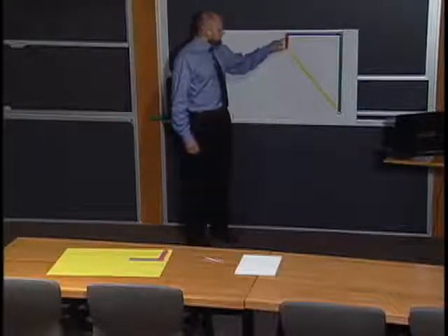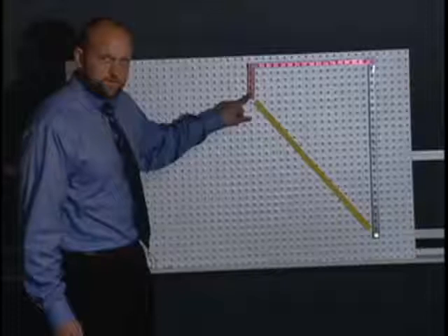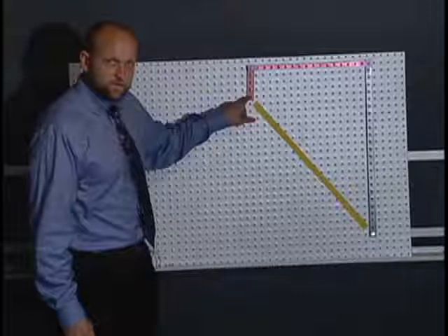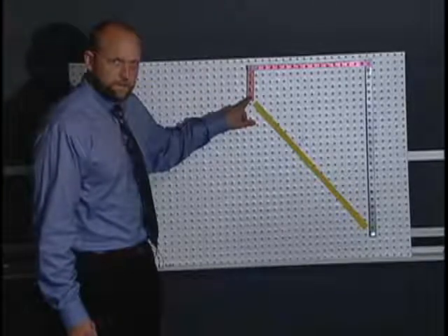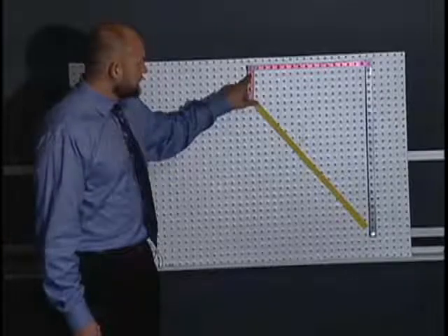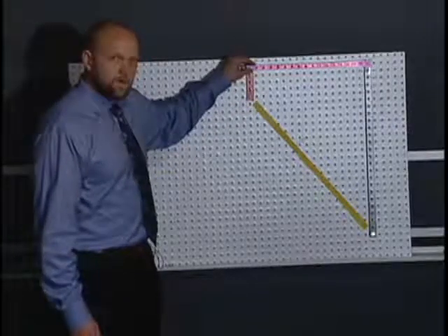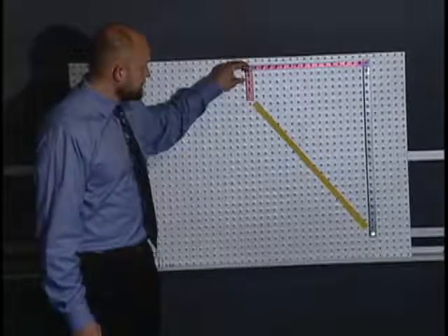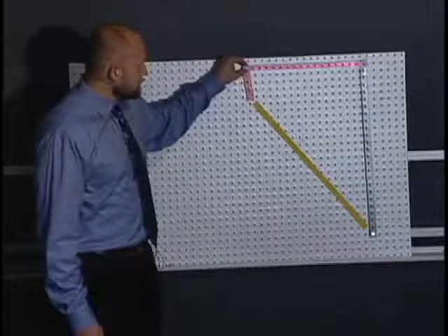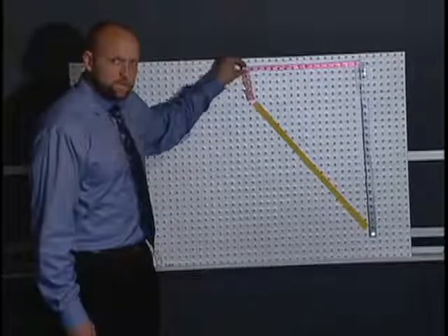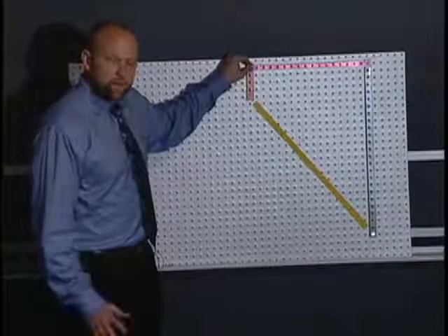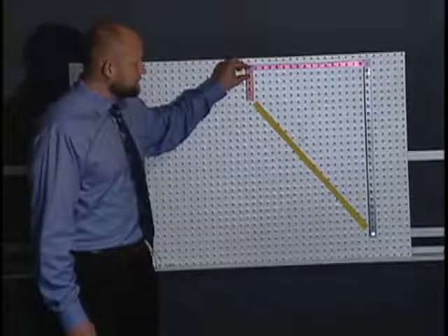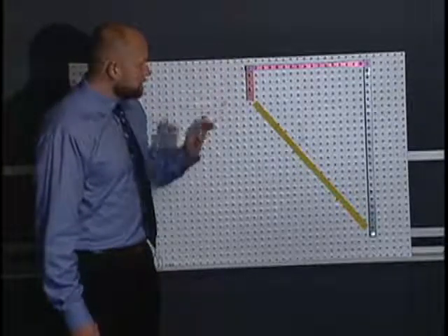What you see here is that I've got one strip. I've colored it red just with a permanent marker, and I've used a screw with some threads in order to fix it to the white background. And then near the top here, I have used a nail to go through the blue link above all the way through to the red link behind. So the nail is going through both, and that allows for relative motion such as what you see here. And I'll have more on this in a handout that goes along with the video module, but I just wanted to comment on these couple of details for now.